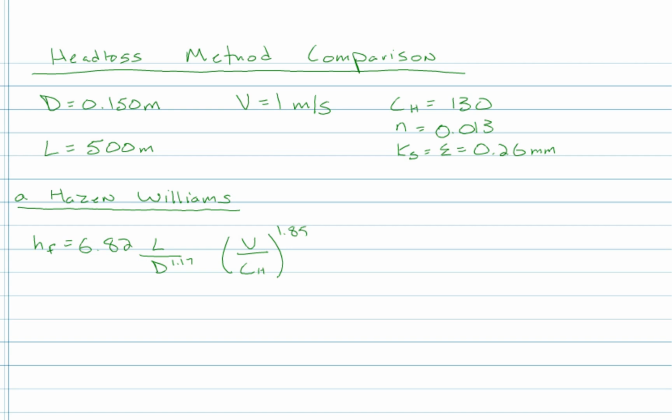You'll notice that there are some pretty bizarre empirical coefficients that we use in the exponents there. And this is an empirical equation that's been developed just observing head loss data for a variety of different pipes. Remember that there are restrictions on the cases where you can use the Hazen-Williams equation. It's not always valid. It's restricted just to water, technically for a certain temperature and for a limited range of flow velocities. But besides those restrictions, it generally gives a pretty good result.